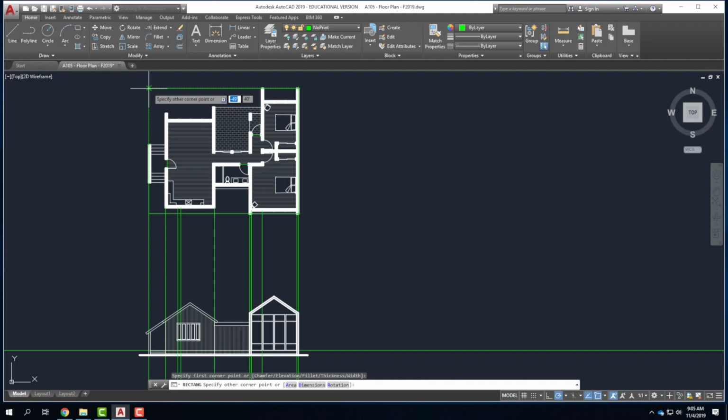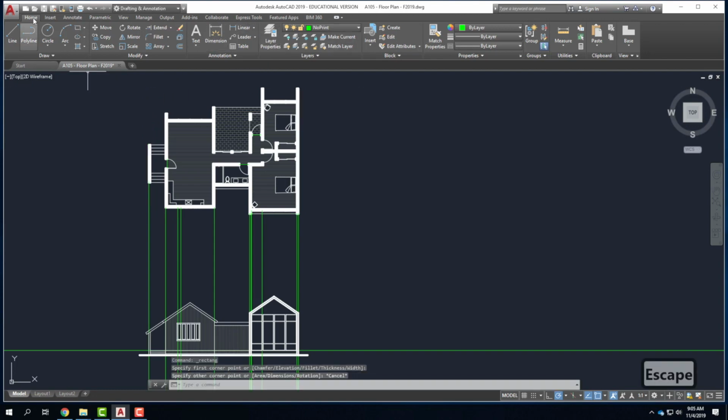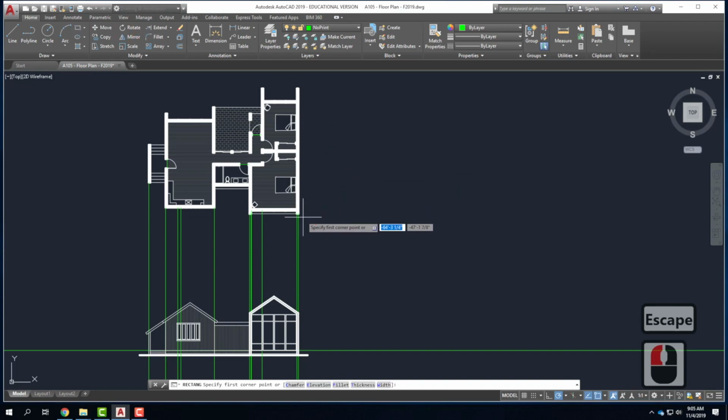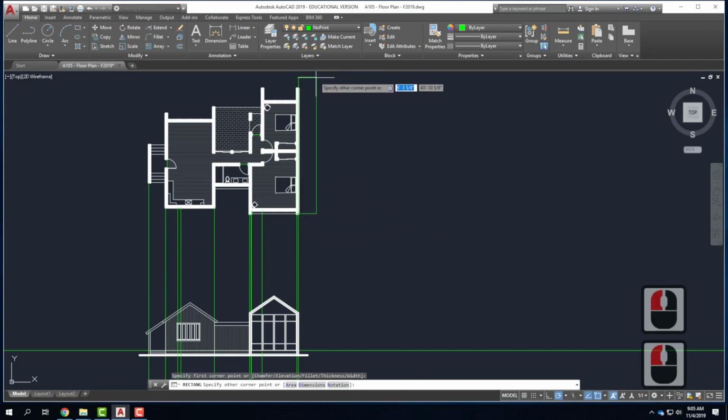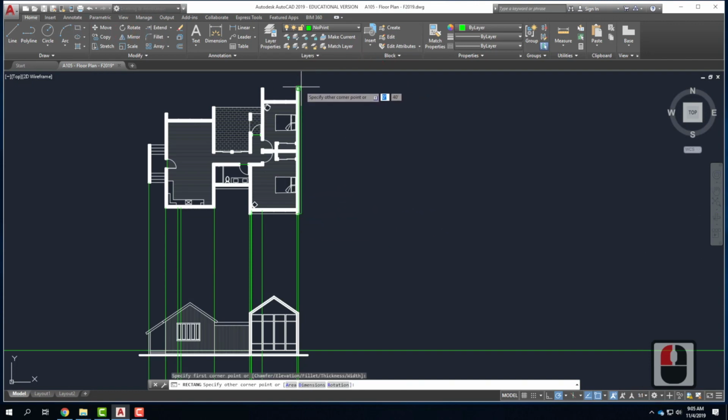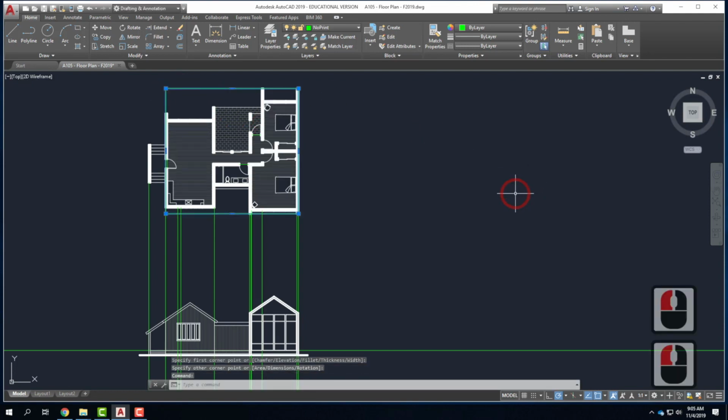So if I set my 2 points, let me show you how I did that one more time. I'm starting here. Then I'm going to go to this point and set a point. I'm going to go to that point and set a point. And as I move up there and there, it will snap. This line is a rectangle that completely contains my whole building.